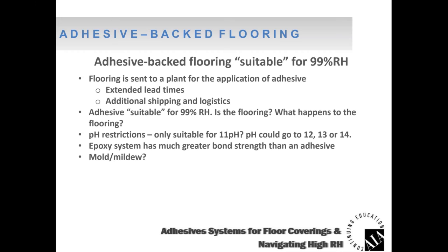So you have a high RH adhesive and floor covering. Ask the question about mold or mildew. If we get to 100% underneath that floor covering and we got condensed liquid, maybe the floor covering and the adhesive don't fail. But ask the question about mold or mildew. Can things start to grow underneath there? What happens? Do we get staining that's involved due to the mold or mildew growing? Okay, ask the question.